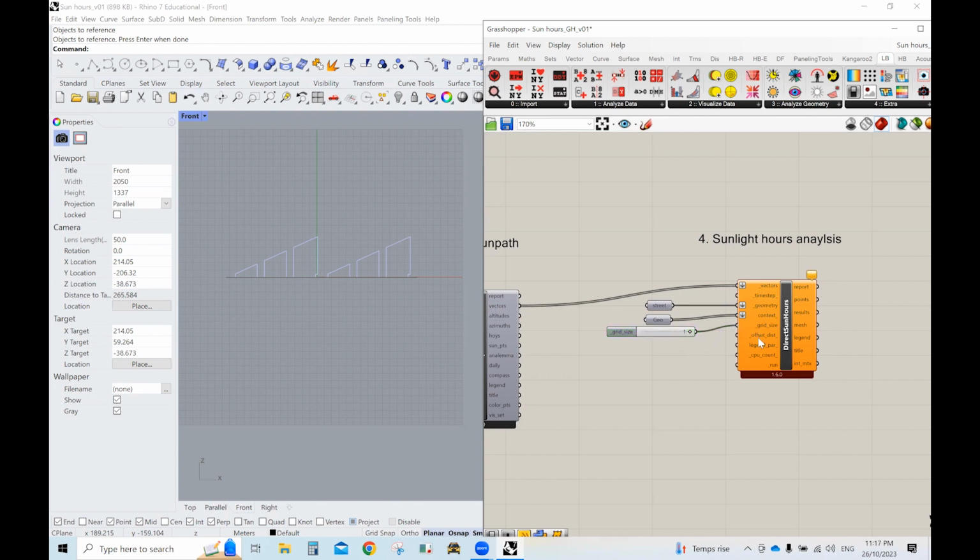Okay, the next thing we need to do is just offset our distance. So this basically just sets the rays just a little bit off the area that we're testing. And this just helps from a visualization point of view. Or if you're wanting to check someone's eye heights, or whatever you were doing, you could offset it from the ground. But we know we're just going to test it slightly off the ground. So we're just going to put a 0.1, just a little bit off.